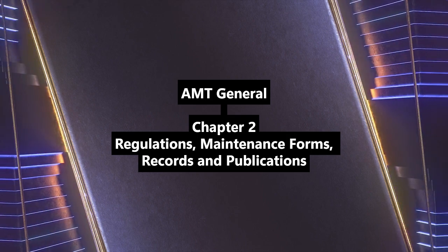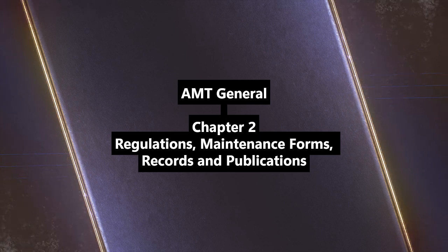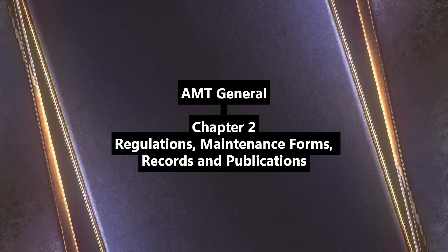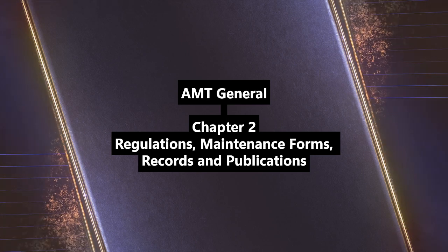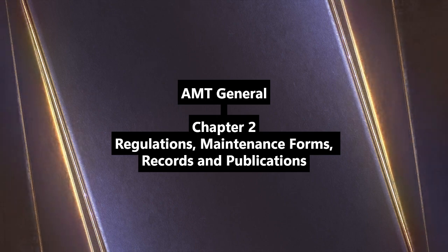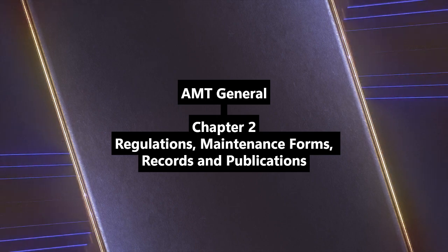Temporary and permanent. Essentially, paragraph A1 covers temporary records: maintenance, preventive maintenance, alterations, inspections. Kept for 1 year or until repeated or superseded. Need description, date, signature, certificate info. And B1 is similar. Yes. B1 mirrors A1 regarding retention time.